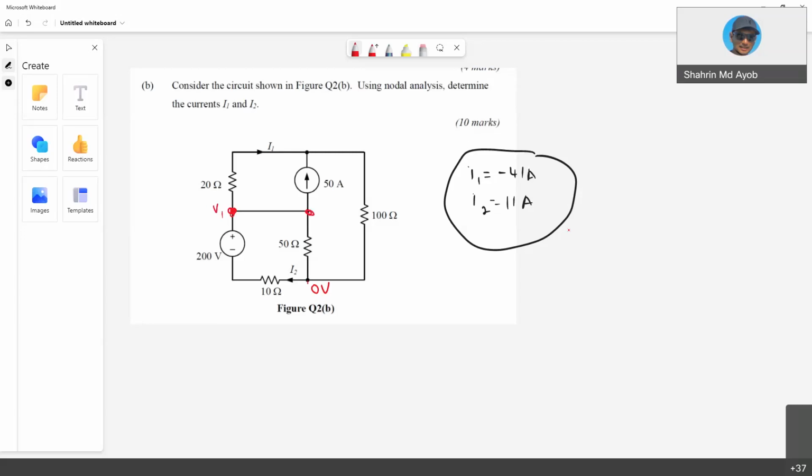This node also. As you can see, this branch doesn't have a resistor, meaning there is no voltage drop here. The current that flows inside here is also 0, because there is no potential difference between this node and this node, as this node is also V1. Current only flows when there is a difference in node voltage.